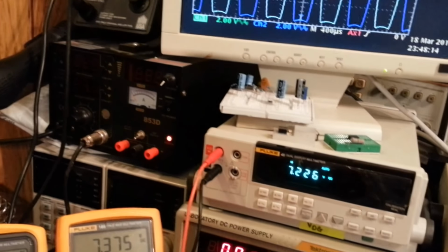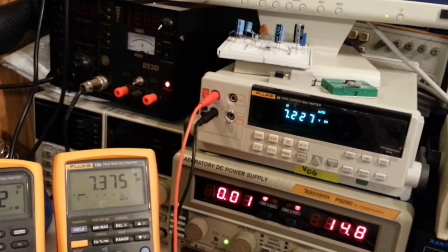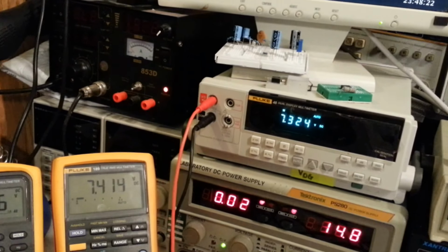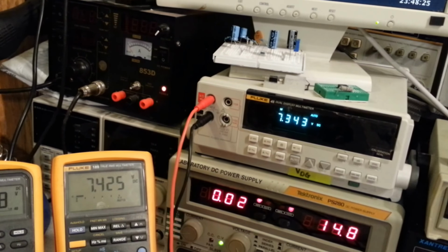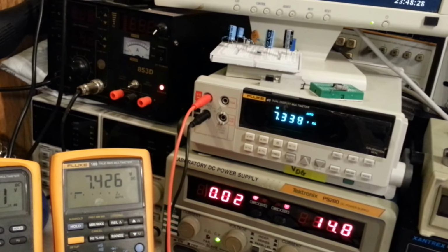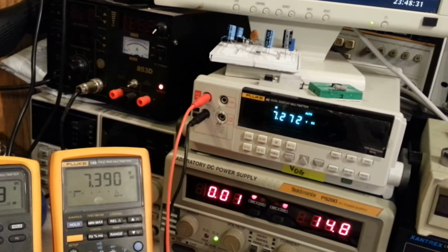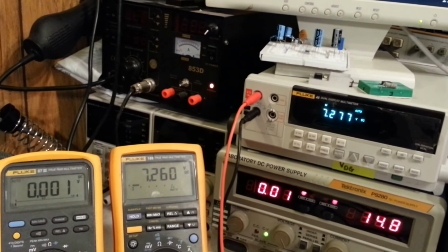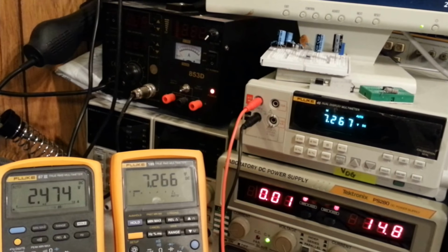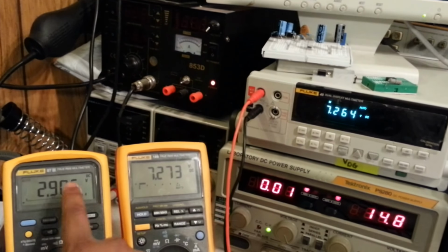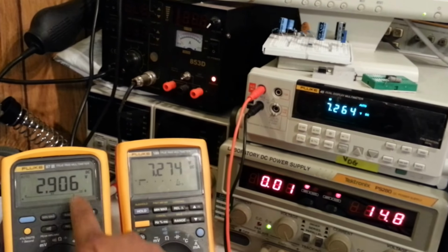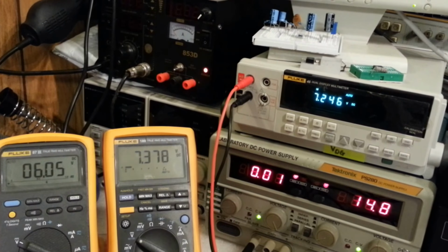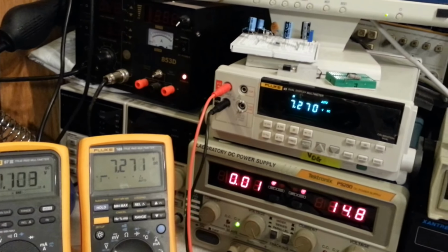And the matching on the transistors is decent. As I vary the gain, you can see there's a slight shift in the quiescent voltage of the two second stage differential amplifier, but not as bad as the first one. And remember, this one is monitoring the current across the current source of the first stage, which tells us what our gain is. So you can see a slight shift in quiescent point, but not terrible.